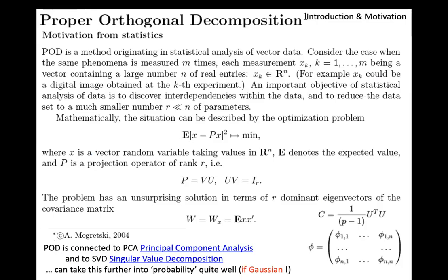And basically, then you use your modes to solve the so-called modal equations that are uncoupled, and you build any response by using a certain number of modes, and you can reduce the computational effort in dynamics. Now, they might be dealing not with linear dynamics where the stiffness is constant, but something is changing. So instead of going for these eigenmodes, they go for these statistical modes.